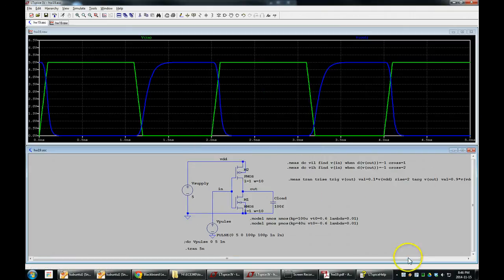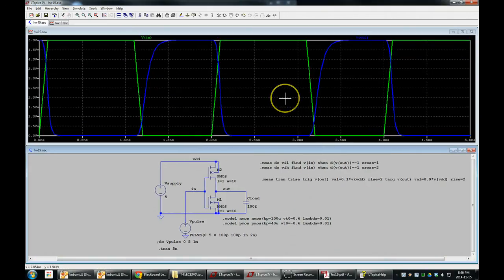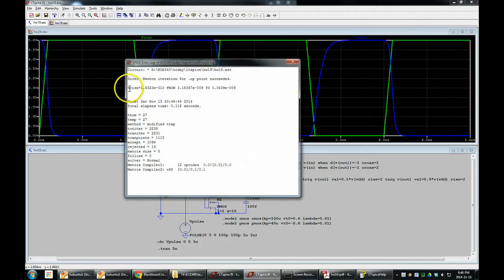See, OK is way over here. Run the simulation. Control L, tRise, 1.6 times 10 to the minus 10. If we move this over here, this is 163 picoseconds. One thing to note, please, when we're doing special logic simulations, is you see how the rise time is pretty close to the rise time that we fed into this gate.